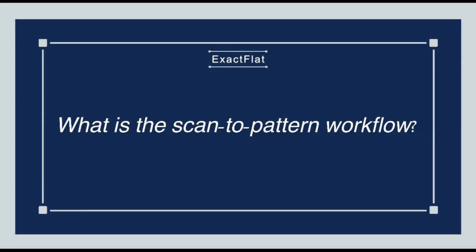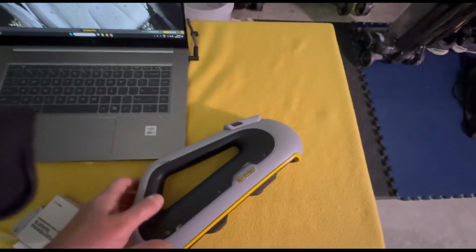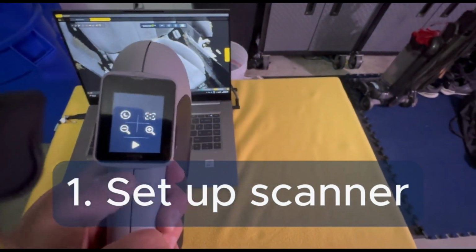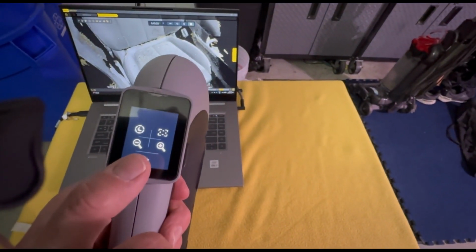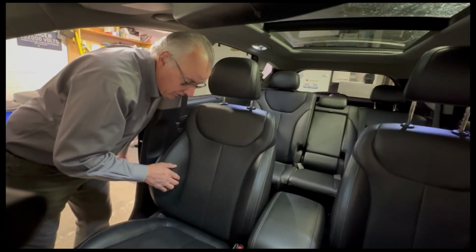Next, let's talk about the scan to pattern workflow. This we can talk about in 4 parts. The first part is to scan your part, which has 3 simple steps. Number 1, you set up your scanner. You can set your scanner up in any place where it is convenient, you have enough light, and you have access to your part.